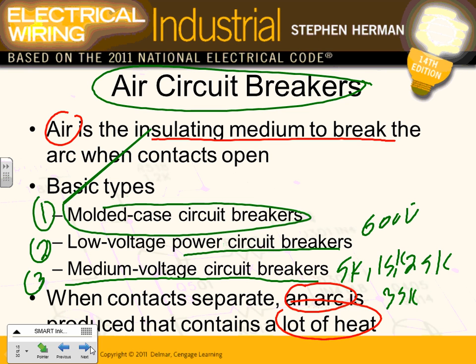Every time you open a circuit breaker, guys, over time, the arc will eat into the contacts, and after a certain amount of opening and closing, you have to go change the contacts, because the arc is brutal.